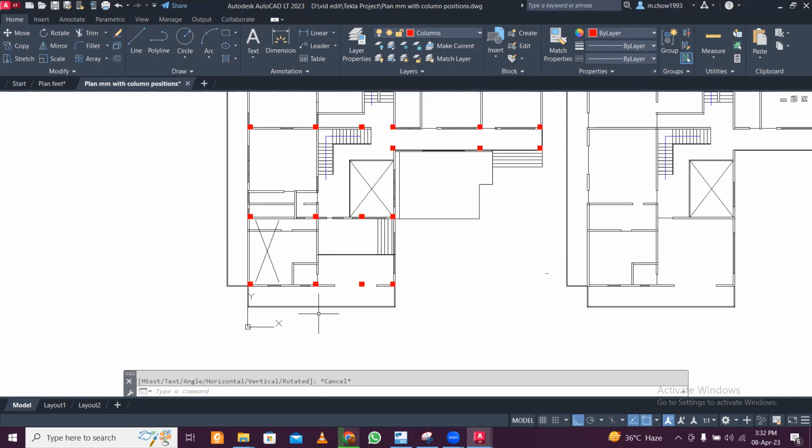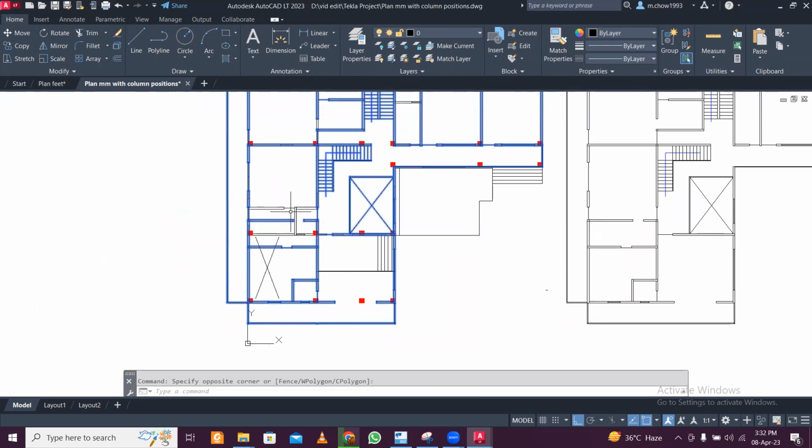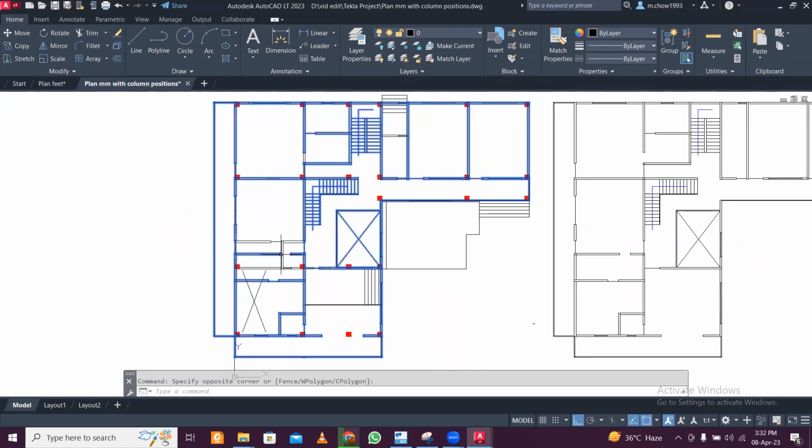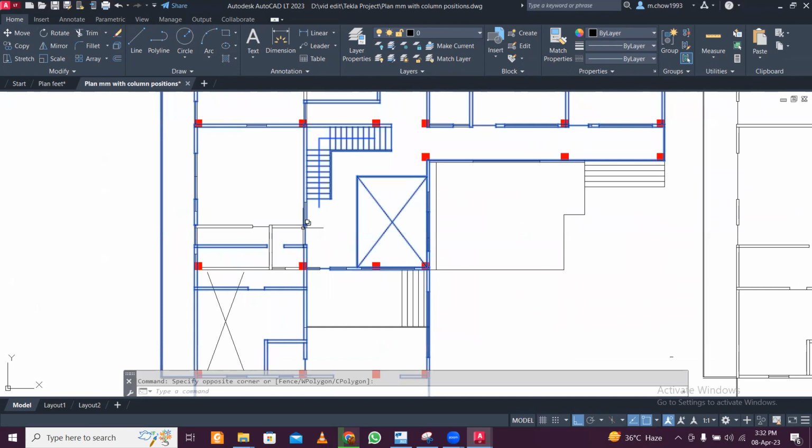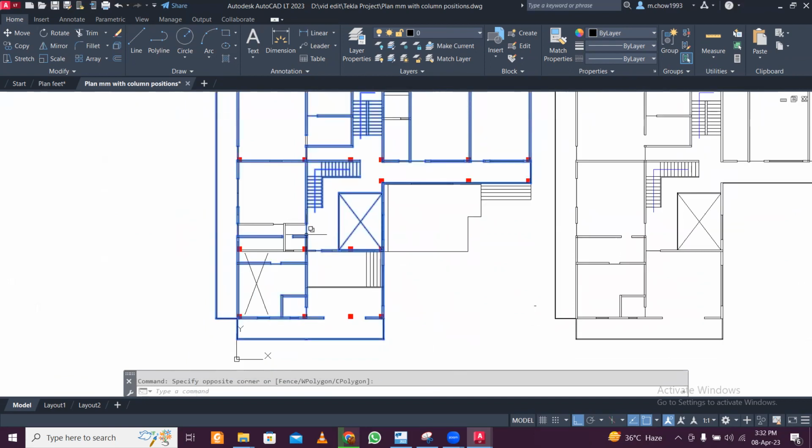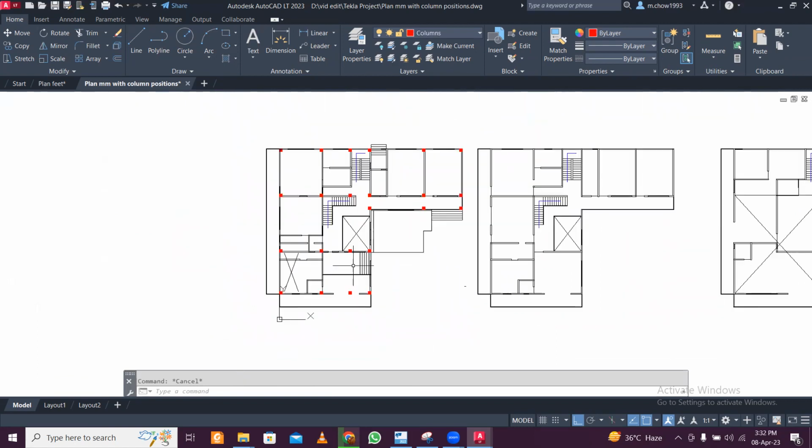And let's see the ground floor and first floor orientation also. This is the first floor beam, first floor beam. Yeah, so the secondary beams are also going to rest on this. So it is just going to be a deeper beam. So if possible, then I think we can give columns here. Okay, let's move with this and then we'll decide later.